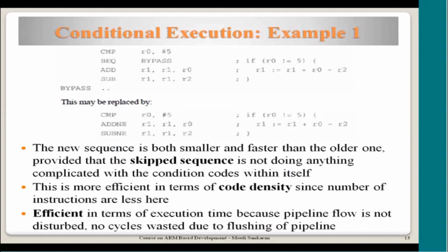You have to remember, whenever you see any instruction, at least we are talking about ARM7, so 3-stage pipeline, you should have it in the back of your mind. Now what happens when a branch is encountered, and assume this was a jump, that means they were equal and it has to go to the bypass.